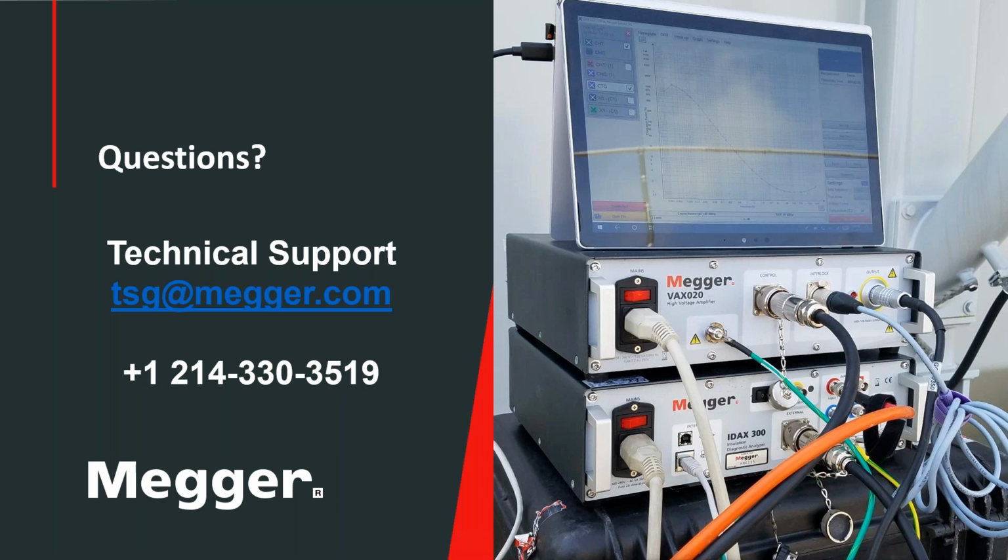One of the nice things that the Idax software has is that when you enter the insulation temperature, it automatically defines the lower range of the frequency. So you don't have to worry about what frequency range you need to pick to get a correct moisture assessment of the insulation under test. From that point of view, it's a great feature available in the Idax software.